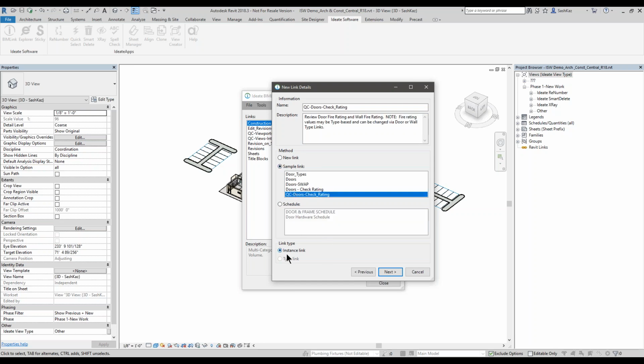And then one of the things that we give you the option to do is export either the instance data or the type data to Excel. We don't intermingle them together because people will start editing the incorrect data. You may think you're editing an instance parameter when you're editing a type parameter, or maybe you're editing the same type parameter for the same exact element in 2 different spots, and you'd end up kind of in this circular motion.